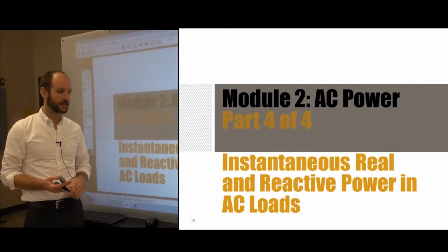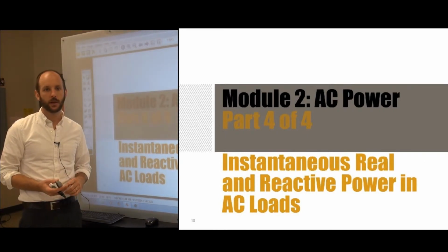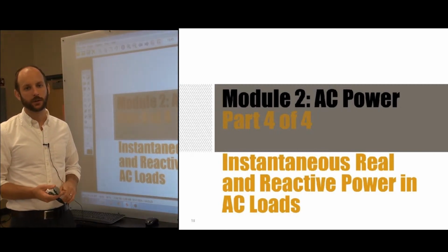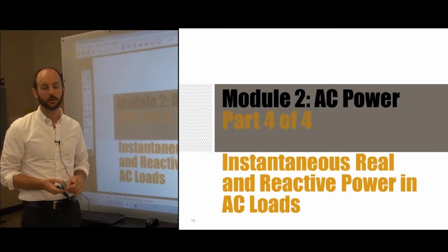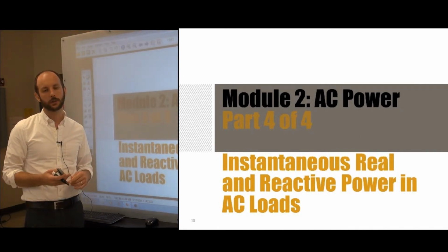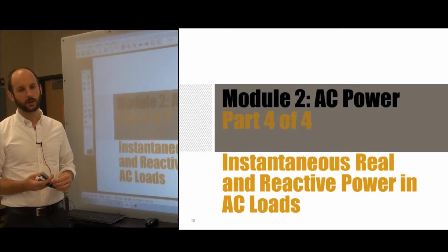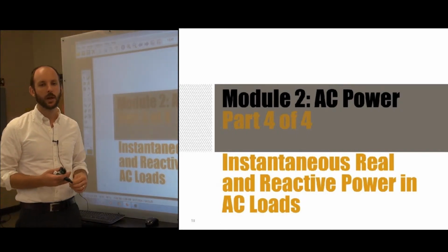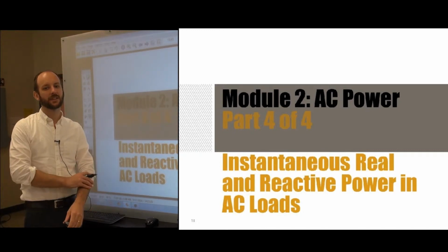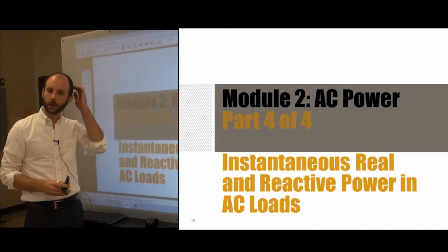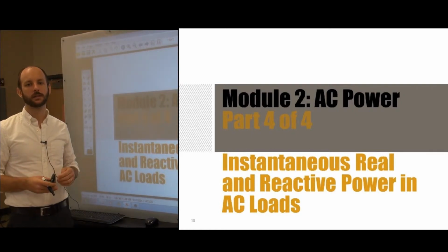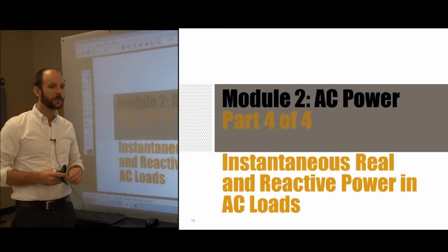If an AC circuit contains any sort of reactance, there is always a power component associated with the magnetic field of inductance and the electric field of the capacitance. The power associated with these two fields is not converted into heat as it is with the resistance, but is stored during part of the AC cycle and then discharged during another part of the cycle. So we say it's stored and discharged during the AC current and voltage cycles.